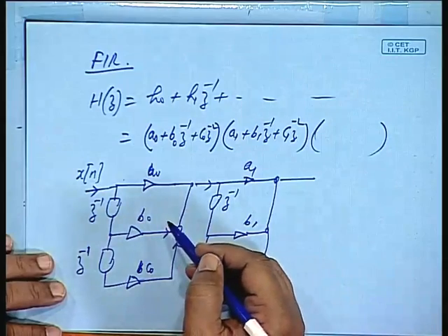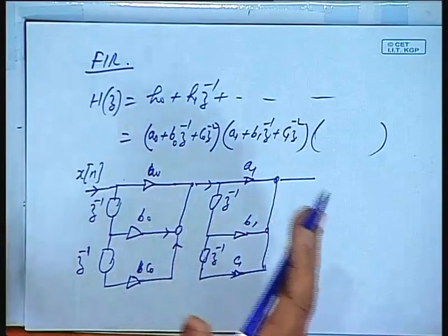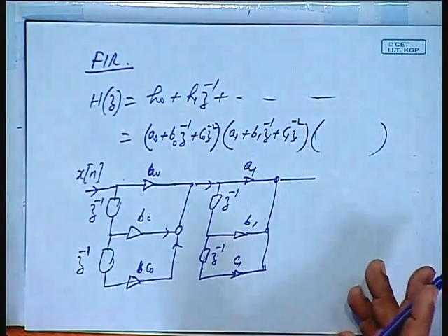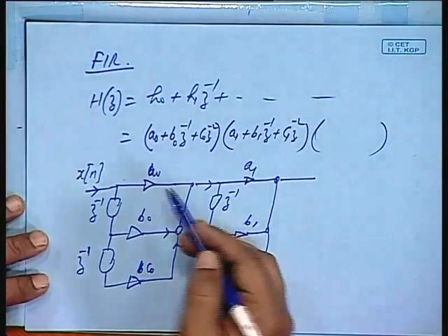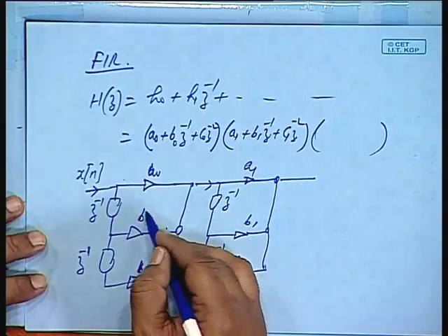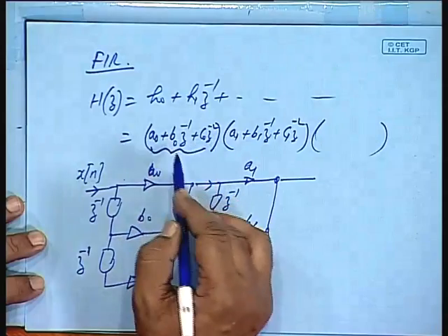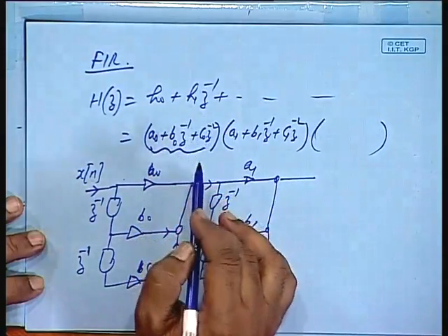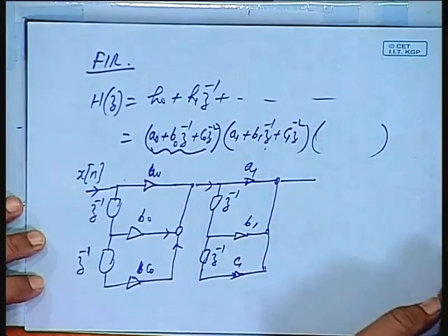In case now these parameters you are trying to finally represent by a finite register length, the memory is finite. So, there will be some truncation error, all right, but suppose any error in these coefficients, any of the coefficients will alter the roots of only these, that is roots associated only with this particular quadratic, it will not be affecting any other root, all right.